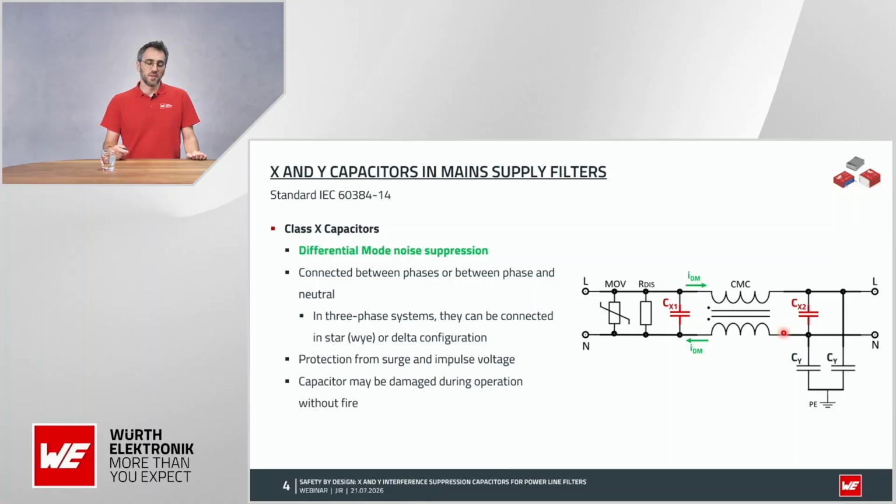And X capacitors are intended to fail open, but it's not a requirement. In general, if they fail short, normally there should be a fuse, so there is no damage to the equipment.